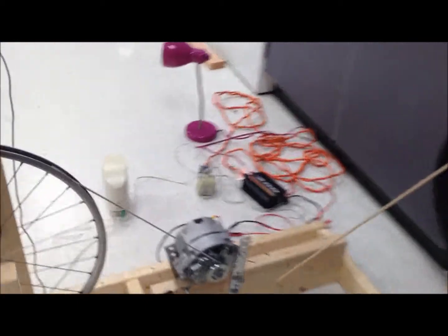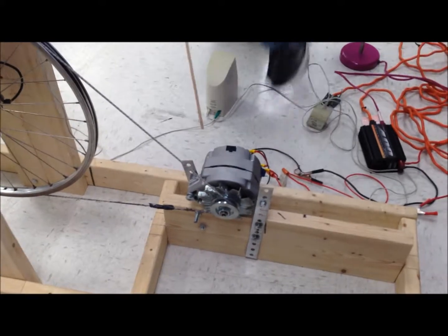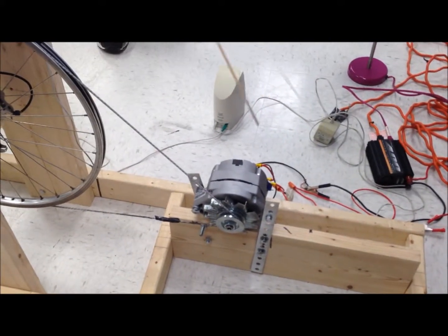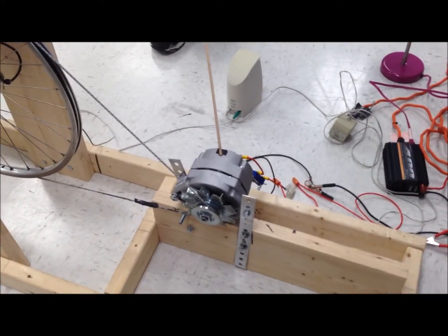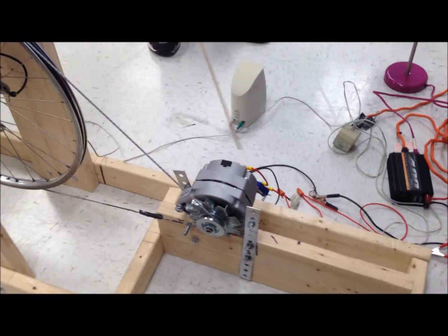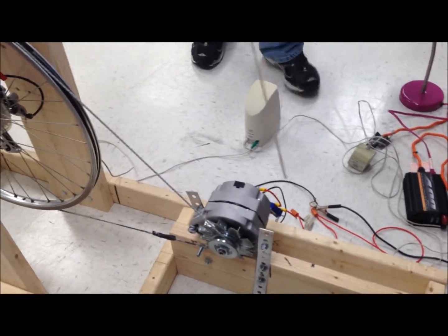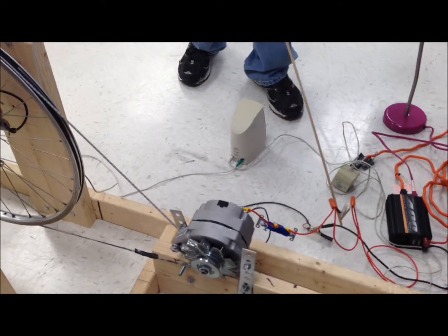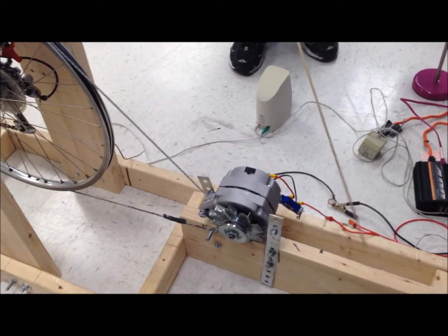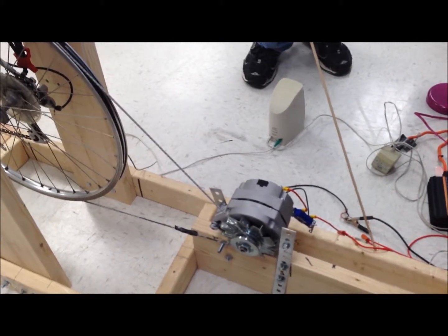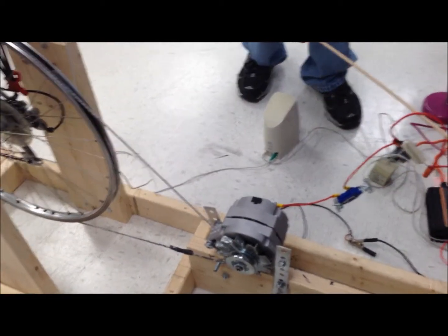The alternator is a single-wire alternator and is self-energizing. What this means is that the alternator needs to reach a quality called a cut-in speed. When it reaches the cut-in speed, it will energize itself and start to create electricity, or start to convert mechanical energy to electrical energy. After the cut-in speed is reached, the alternator can spin at any speed and still convert energy. The cyclist needs to pedal vigorously until the cut-in speed is reached, and then the cyclist can begin to pedal at a more comfortable pace.